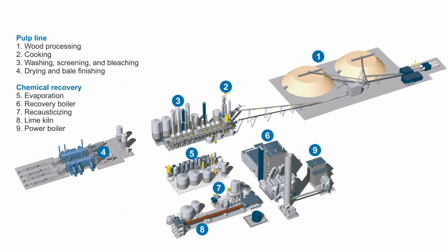Kraft pulping is energy-intensive and it provides a less efficient use of wood resources than desired. Catalytic methods offer a viable alternative to increase cellulose fiber yield by improving selectivity, reducing energy use and eliminating the formation of odor-causing mercaptans associated with kraft pulping. If successful, catalytic methods will improve yield, reduce fiber waste, reduce energy use, lower the cost of bleaching and decrease the cost of air emission controls.